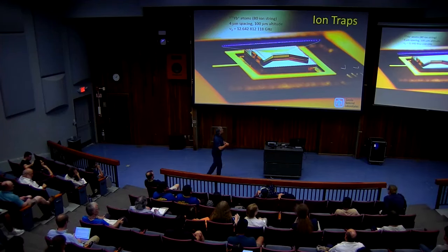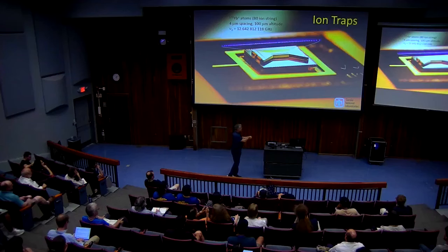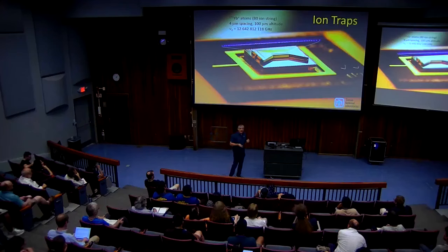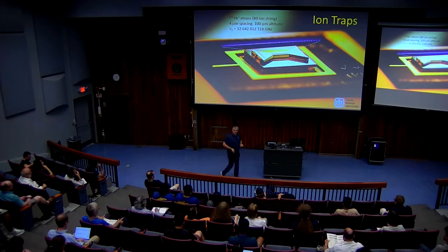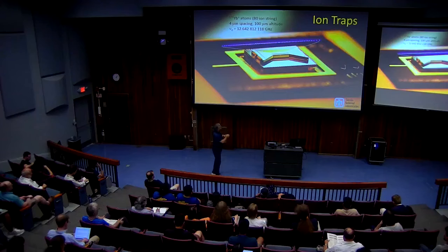So this picture is a lovely ion trap that is built out of, it's a very complex silicon device built at Sandia National Labs. They have a wonderful quantum computing group at large, including an ion trap group. And this is a very complicated chip. It has many layers. I won't get into it, but there are about 100 electrodes. They're plated with gold at the very end so that we can apply potentials that create electric fields that suspend atoms.